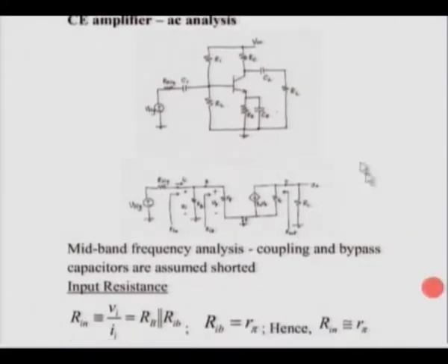Now, what we have drawn here is the common emitter amplifier. We have the signal source here, VSIG and an RSIG here. In general it is always better to keep the Thevenin equivalent resistance of the voltage signal source. Now, this is connected to the common emitter amplifier through a capacitor. Now, why do we need this capacitor? What will happen if I do not connect this capacitor?